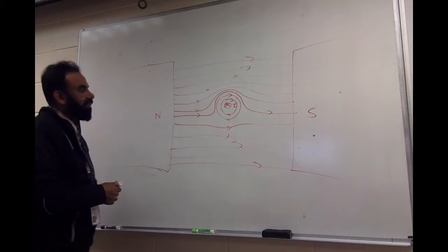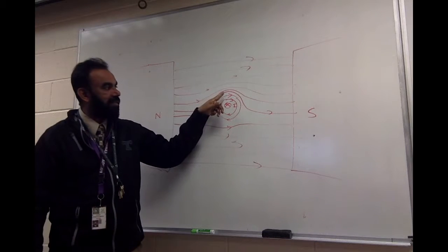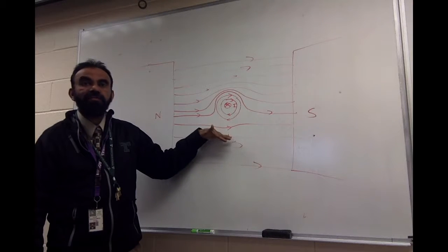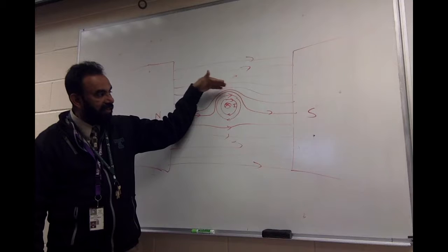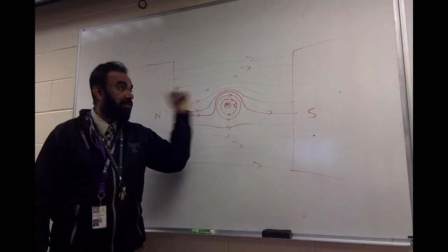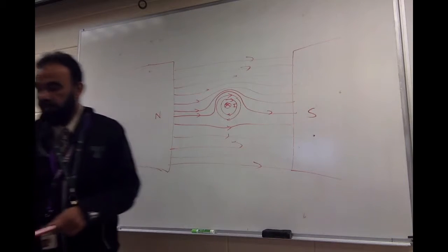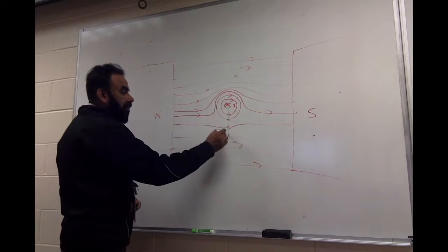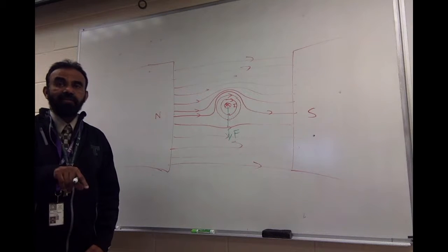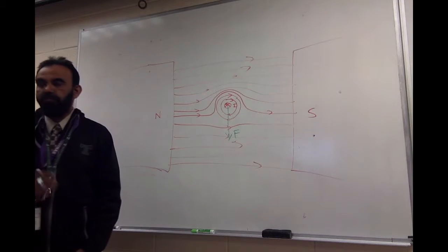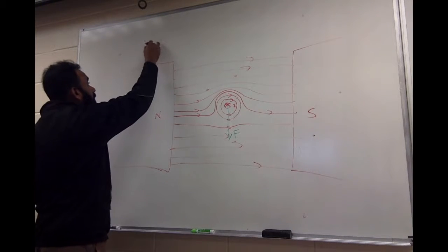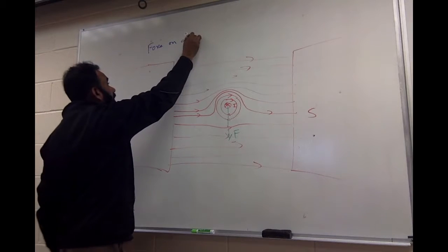Okay. So what happens is, you can see the magnetic field lines are getting crowded over here and very less dense over here. So the magnetic field strength is pretty high in this area, and because of the crowding of lines, this wire will be subjected to a force because of the extra crowding, and the force will be downward. The force is going to be downward, and that's what we call as the force on a conductor carrying current in a magnetic field. Force on a conductor